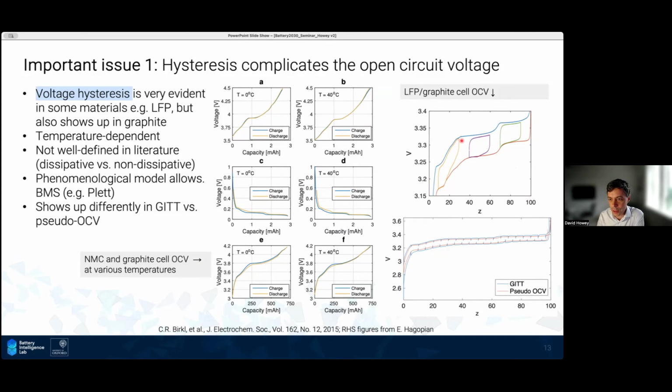These are slow charge discharge measurements. But then also interesting things happen. If we go to the low state of charge region and do a small charge discharge around 20%, we get this orange shape. We do the same at 50%, we get this purple one. Do the same at 80%, we get this green one. And you can see that the shapes of these are slightly different to each other, and they don't quite reach, in this case, the blue curve at the top. So there's definitely interesting and strange things going on with hysteresis that we're still trying to understand in our group and as a community.